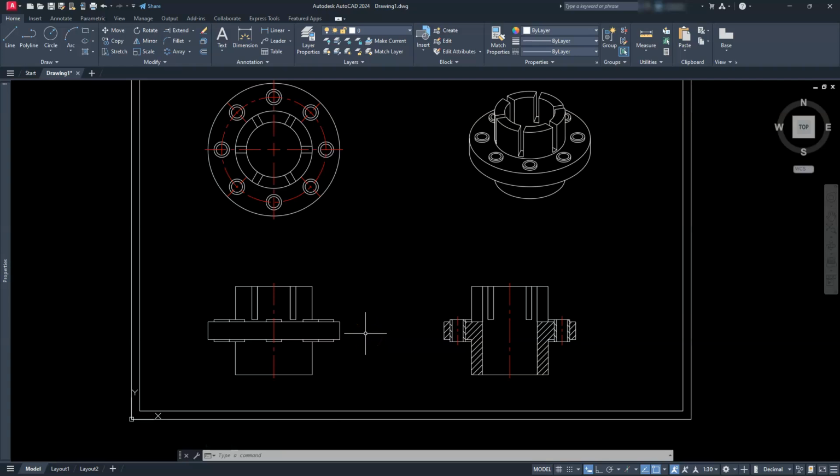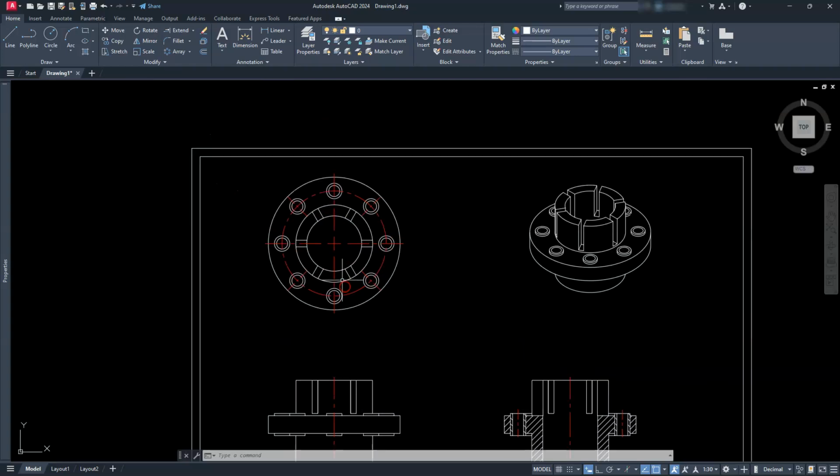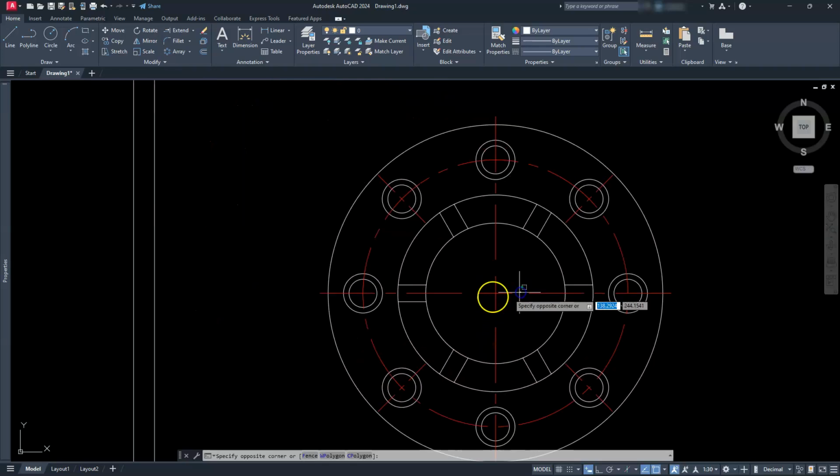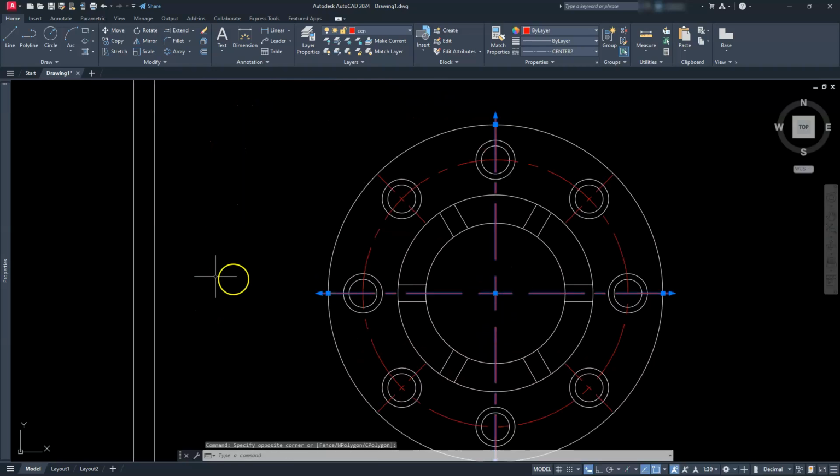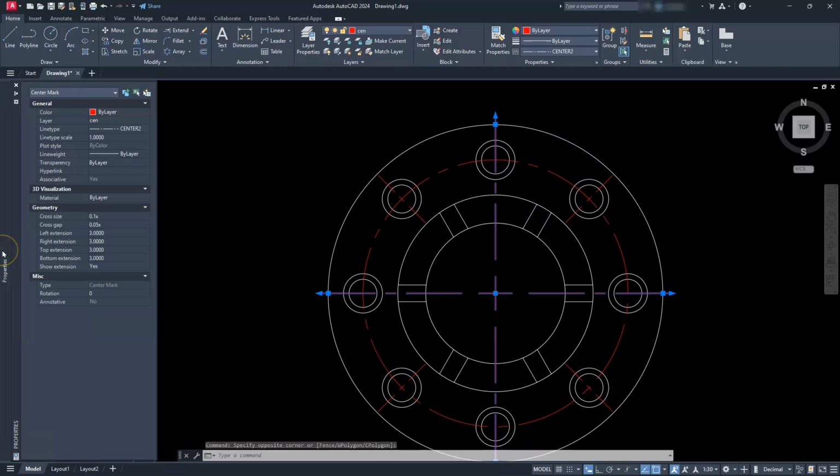And now we've finally made it to the last parts of this where we need to put a center on there. I mean, a section line and things of that nature. But before I do my section lines, let's go ahead and extend this one. So I'm going to select my center mark here. I'm going to go to the properties window, and you can see where it says left and right extension. Let's go ahead and make these extensions just a little bit longer. So I'm going to make it 6 on this side and 6 on the other side.